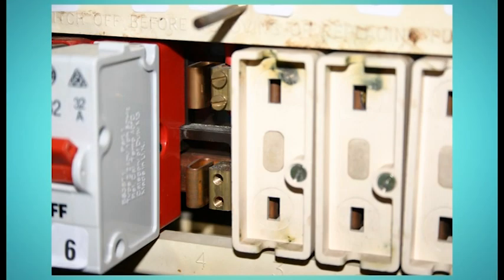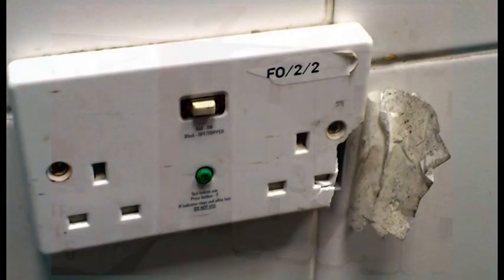Tony, with regard to the C1 code, what would you do if you found a defect of that level? Well, a common cause of a C1 is an exposed live part. It could be a fuse board with blanks missing, where fingers can get inside. It could be a broken socket. These cannot be left for the full report to be completed before pointing out the danger to the client, verbally if possible, and then confirmed in writing.